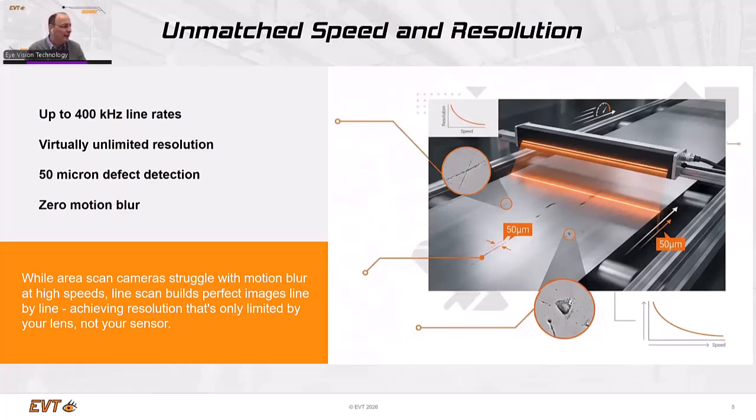And of course, you also find some faster ones, which allow you to run at very high speeds with a very high resolution in the moving direction. The line scan cameras are also available with a very high number of pixels in the line. Normally you get line scan cameras from the very low end, maybe 500 pixels, but you also get them with 16,000 pixels and more.